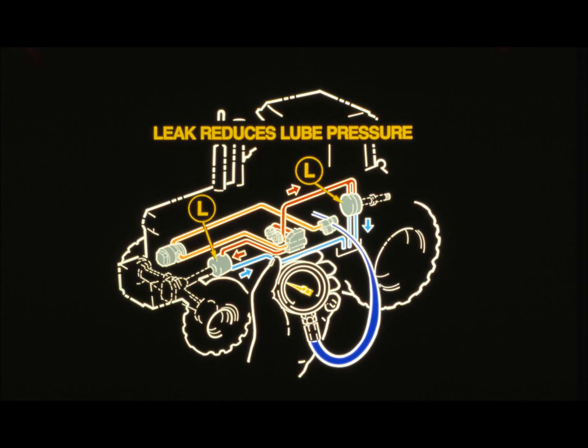The PTO clutch and brake release and the MFWD clutch all operate on system pressure oil, dark orange. Normally, very little oil flows to them. If there is a leak, oil flow through the leak will reduce oil flow to lube. Excessive leakage reduces lube pressure by more than 3 psi. If there is no leak, operating the clutches and brake release will do little to affect lube pressure.